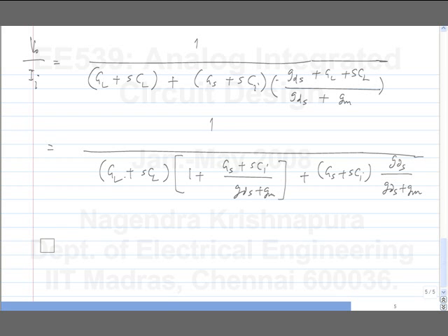See, the only thing I will say is, what is the effect on the input impedance because of GDS? It increases. Yeah. So, the input pole goes to a lower frequency. And the output impedance was infinity.